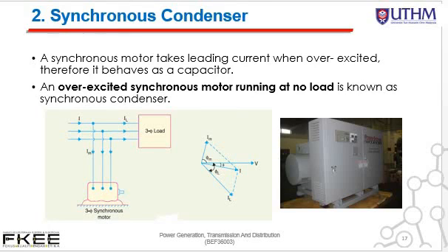By adding an overexcited three-phase synchronous motor in parallel with the three-phase load, this is the synchronous motor and this is the three-phase load, the synchronous motor will act like a capacitor, and the lagging reactive current component produced by the load